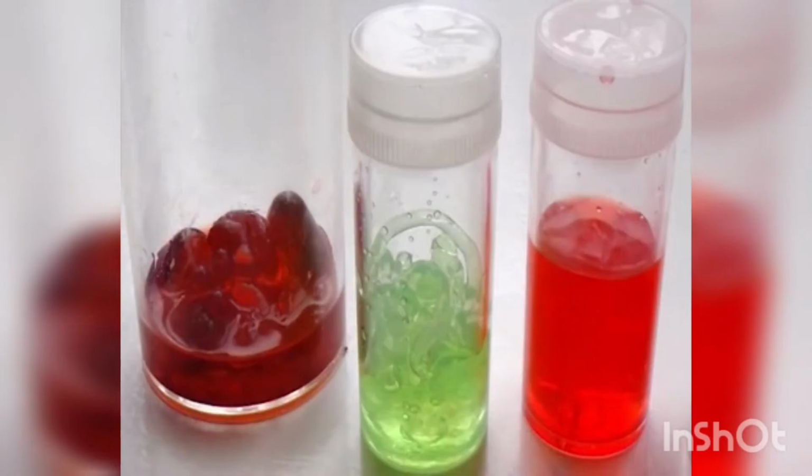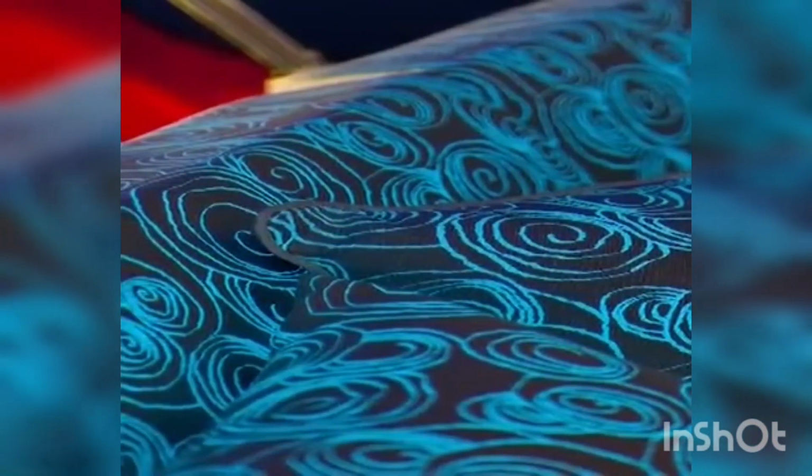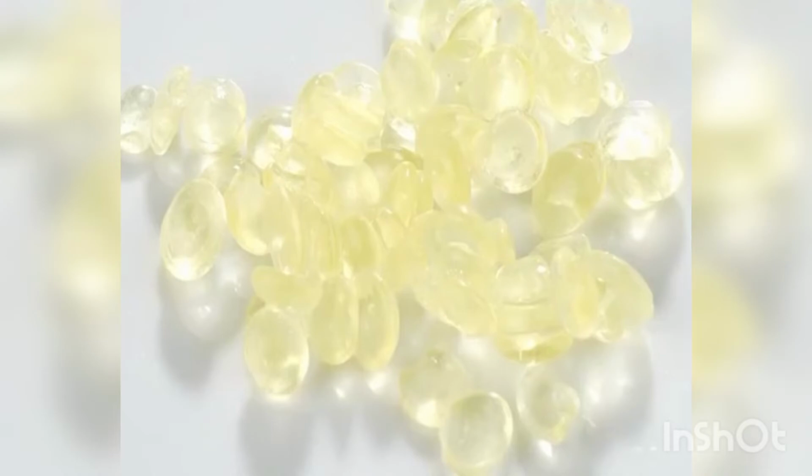Nowadays, gums or alginates derived from seaweed are preferred because they are easier to wash out and do not themselves absorb any color and allow better penetration of the color. Most pigment printing is done without thickeners as a mixing up of resins, solvents and water itself produces thickening.